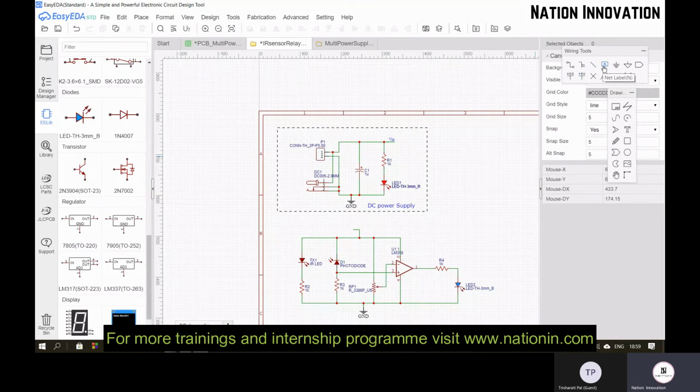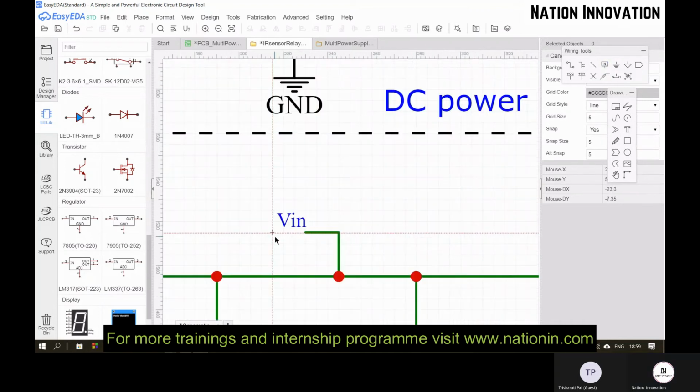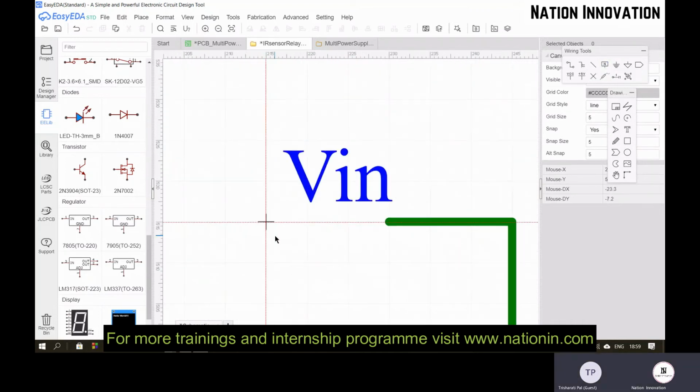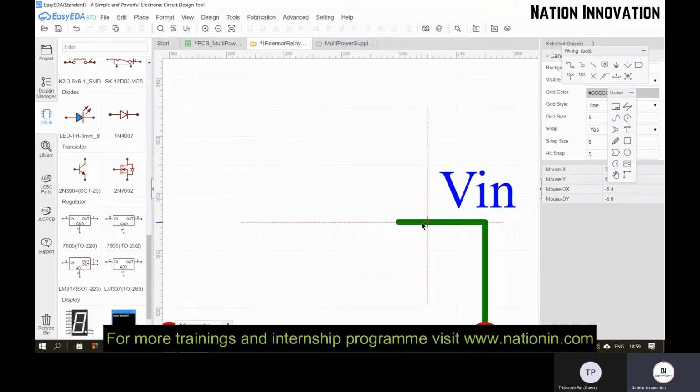You can press N on your keyboard. That is a shortcut, or you can go to this wiring tool and select this net label. It has a positive symbol here, which has to be placed on this wire. Then only the internal connection will be done between your power supply and sensor.